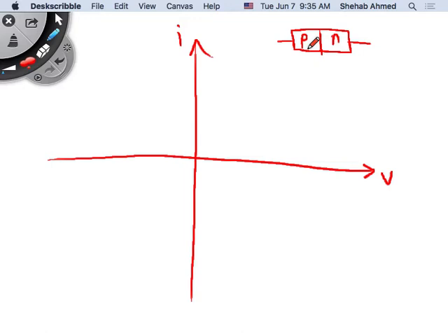So assume this barrier voltage is very small, ideally 0. Then I have a characteristic of the diode in the forward condition that looks like this. As soon as I have a voltage V in the forward direction equal to a very, very small value, I can conduct an infinite amount of current. And we said that this amount of current should be limited by your external circuit, right?